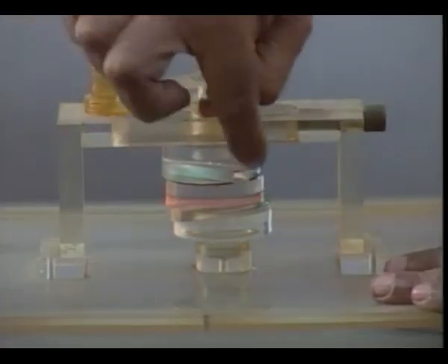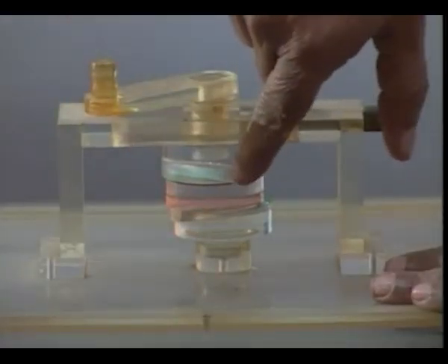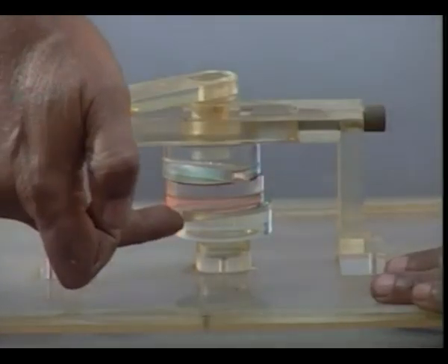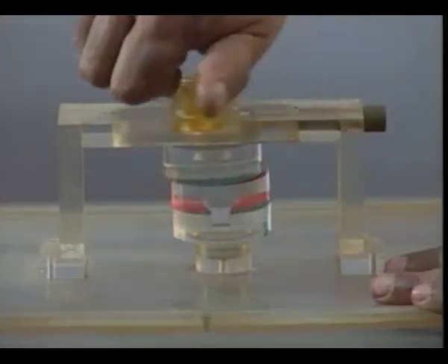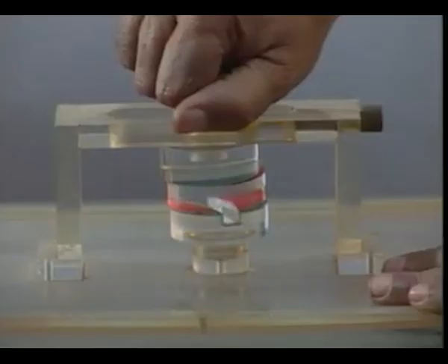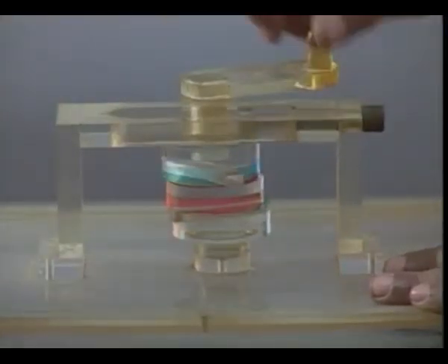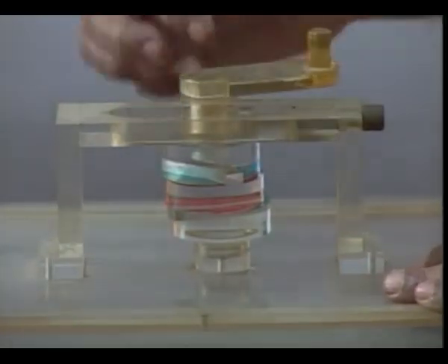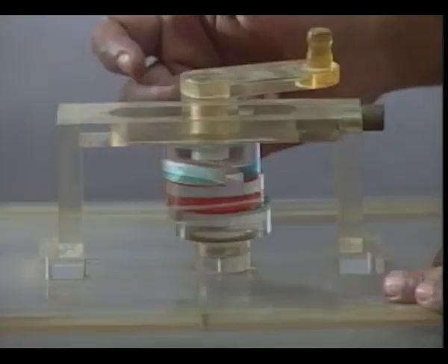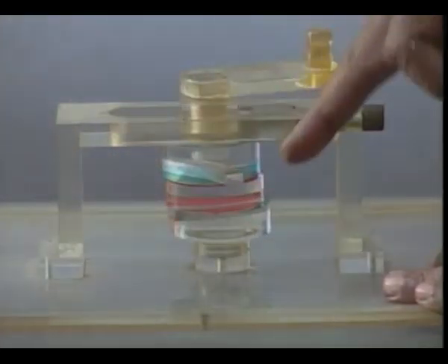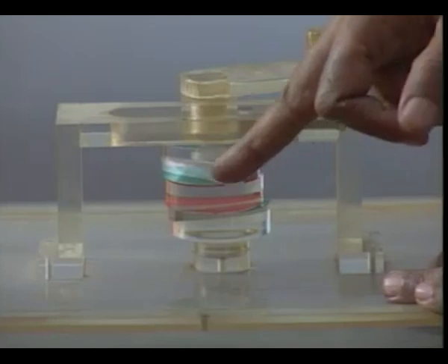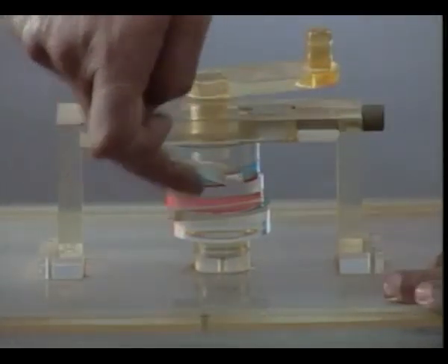This intermediate member moves in and out in this prismatic pair and also at this prismatic pair. Of course, this coupling is good enough to transmit power only when the offset between these two shafts is not very large, because a lot of power is wasted in friction at these two prismatic pairs.